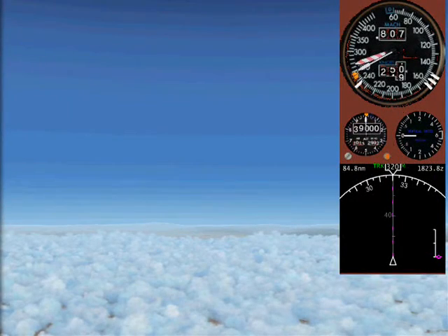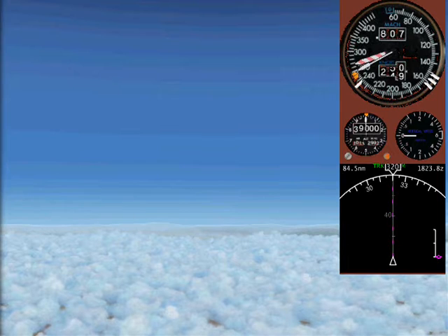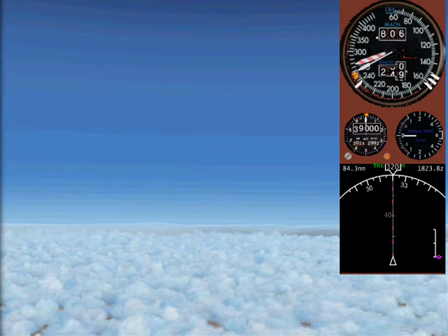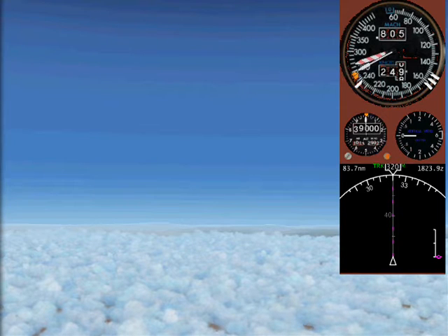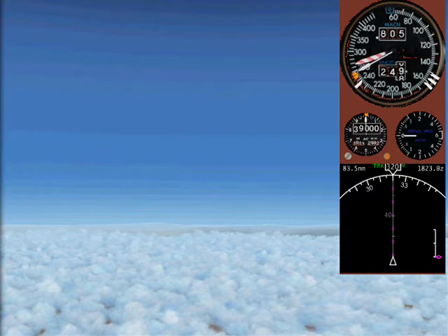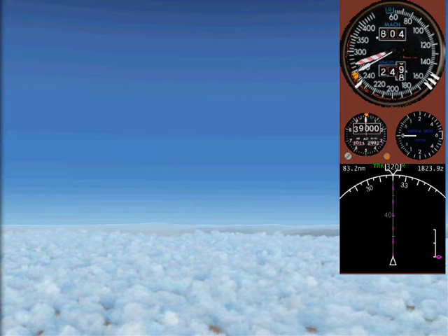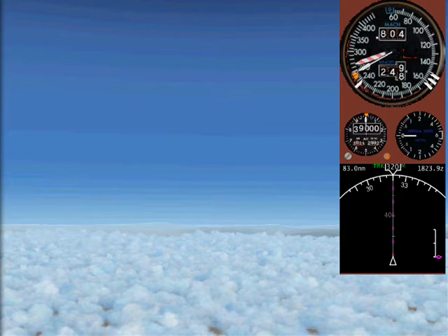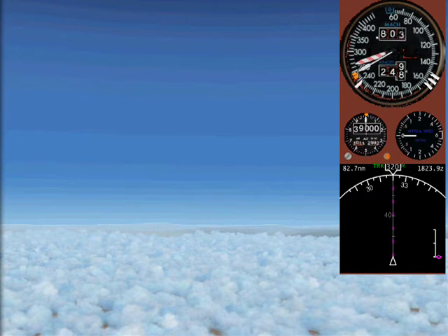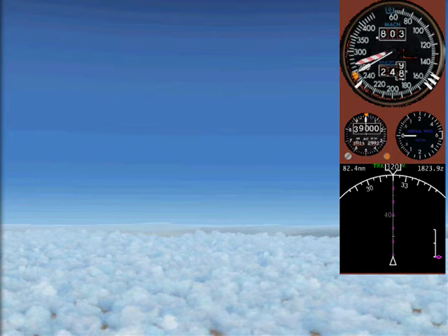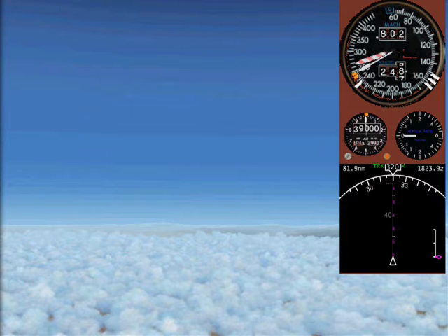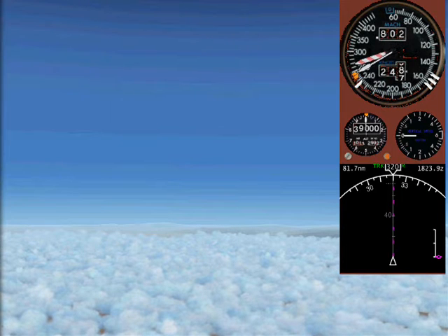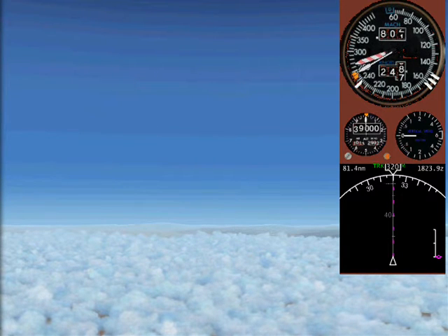This jet is cruising at 39,000 feet at Mach 0.8, indicating 250 knots. True airspeed is slightly below 460 knots. The striped needle, called the barber pole, is indicating 265 knots, which at this altitude is the indicated airspeed at Mach 0.86, which is the Mmo for this airplane. Staying below the barber pole guarantees that both Vmo and Mmo will not be exceeded at any altitude.